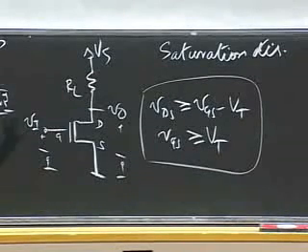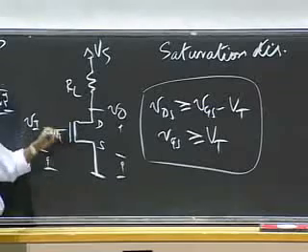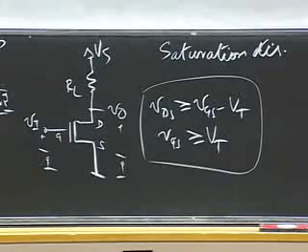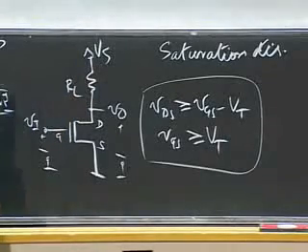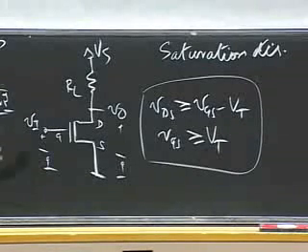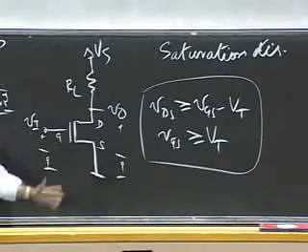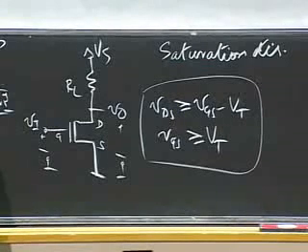Okay, in future courses, you may actually see the MOSFET used in other regimes of operation for a variety of reasons, but in 6002, when we talk about amplifiers and so on, we will be adopting the saturation discipline. Okay, and homework problems and so on will state that: assume that the MOSFETs are in saturation.